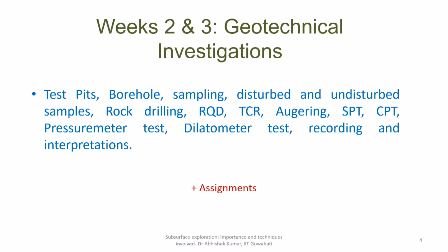Then when we go for in situ investigation, the first thing which we have to do is collect the soil type which is available near the surface. So, primarily we will be conducting based on test pits. I will be talking about what test pits are, and what important properties one can understand from test pits. Then we can go with detailed investigation, starting with boreholes, borehole drilling, then collecting soil samples from different depths, then mapping the groundwater table, and soil classification. So, all those things will be discussed in detail.